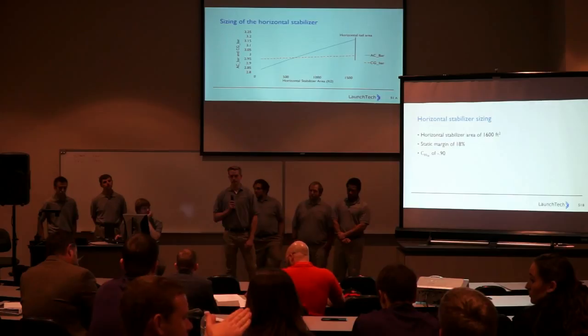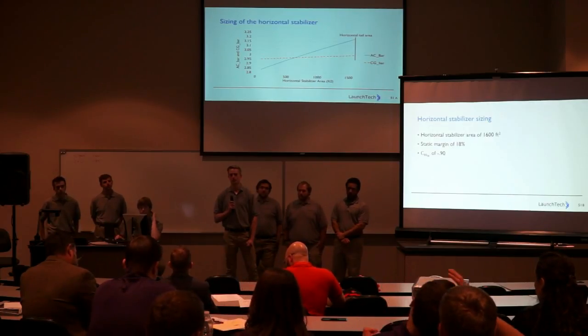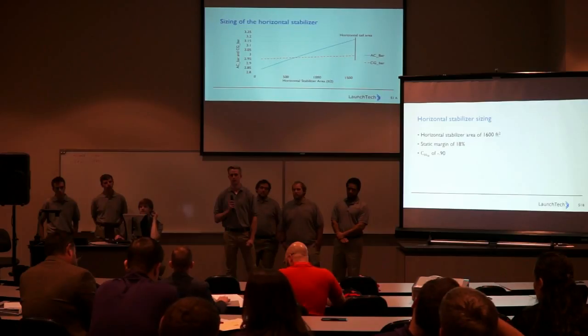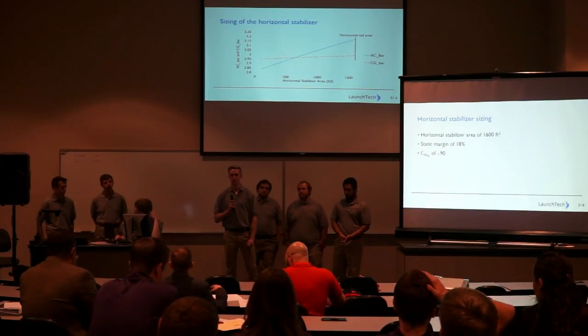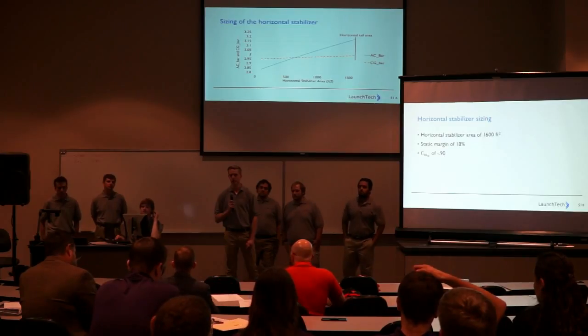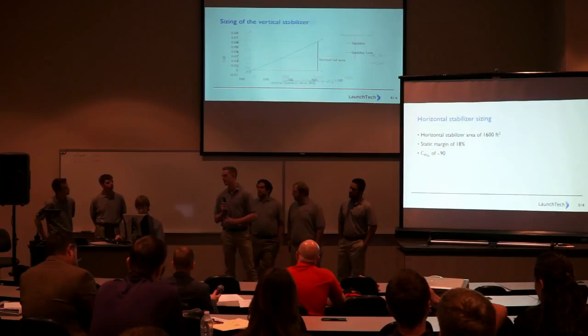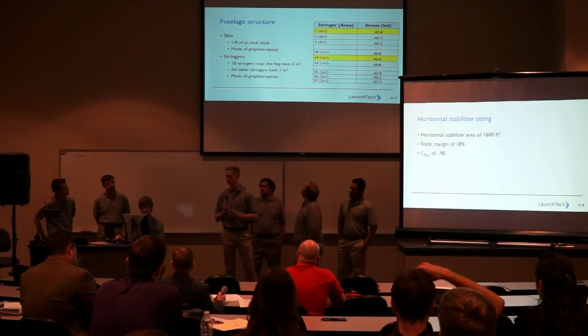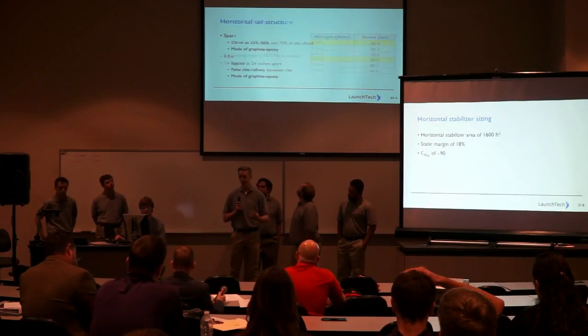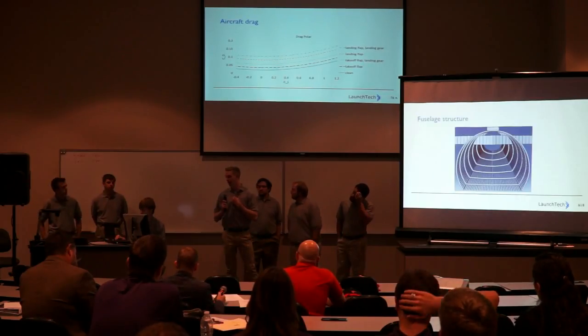Okay, and kind of the same thing with the drag analysis. You said that your dirtiest configuration was gear deployed and flaps, but really, is it your dirtiest configuration? What we estimated, and if you can go into the drag polar, what we estimated for the performance of the power plant was a CD of 0.15.